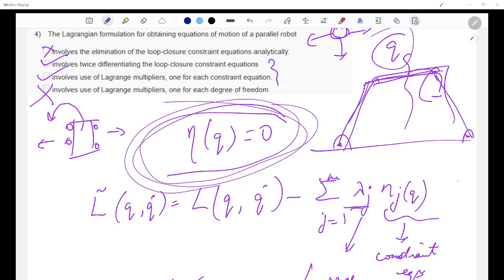So a car is not a holonomic robot. It is a non-holonomic system. A robot is holonomic if the number of independent control inputs equals the number of degrees of freedom. That is something in configuration space. I won't go much into that. But an omnidirectional mobile robot is a holonomic robot. For lateral movement, you need to consider the velocity as well. Here, velocity also comes into the picture. It's not just about the position anymore. It is also about the velocity now.